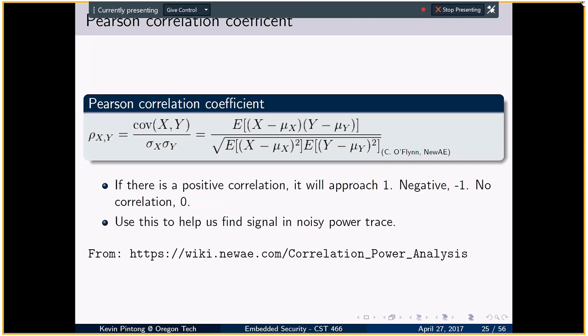All right. So we talked about side channel attack, then we went to simple power analysis, which we'll do in class or sometime. I'll take a video recording of it. Now we went over differential power analysis, and now we're going over correlation power analysis. We got the Pearson correlation coefficient, which is the covariance of two different signals.